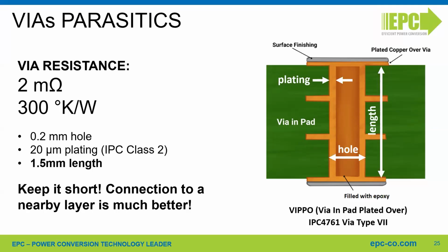The first line of action is to tune the gate resistors to avoid excessive overshoot. And then, of course, you can think to use a Zener diode, but the response time is not always enough to provide a full protection of the gate.